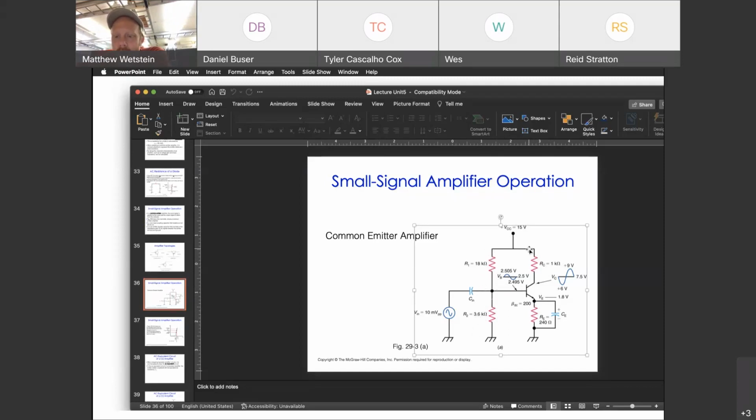And then we also can figure this out, because whatever that IC is, IC times RC plus IC times RE subtracted from 15 volts is going to be the voltage drop across our capacitor, etc. So, knowing all these, and again, the relationship between whatever IB is, IB times beta is going to give us IC. So those are the relationships that pin down how the DC part of this circuit works. And now I think we can talk a little bit about the AC.